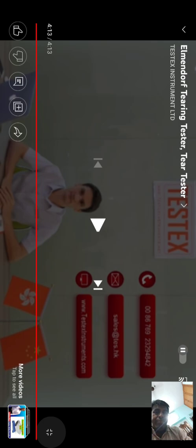Observe one more time. This is simple, very simple. The video repeats the procedure: cut the sample, fasten it in the equipment, release the heavy hem to tear the fabric, and read the strength data from the indicator. This is very good. Just 40 seconds.